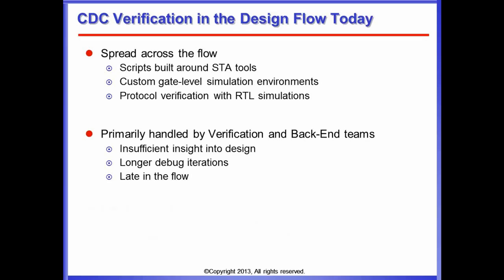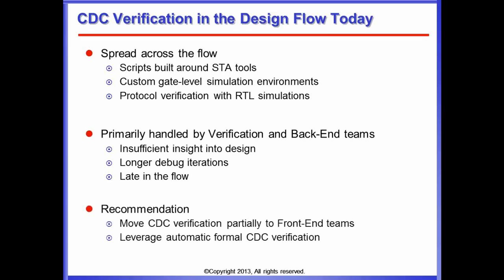in any term. So what we recommend is to move to a dedicated CDC verification tool, and also automate the verification of the CDCs, as there's this paradigm or rule that the front-end designer shouldn't verify his own block with his own parameters and test bench, right? By automating that, you can move the verification of the CDC to the front end and get a more error-free, more robust design in the back end.